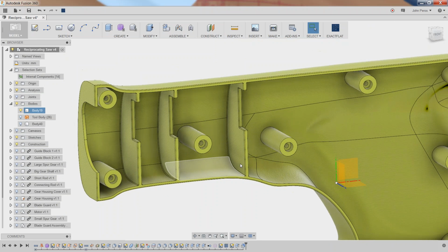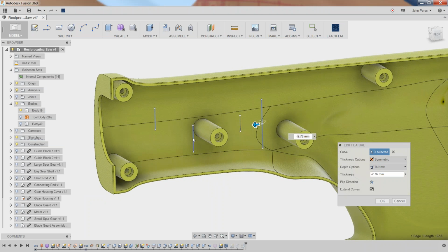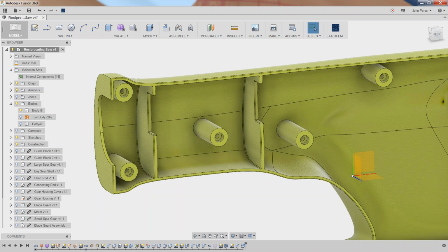those features. Now, this is a really robust way to do fillets, because if I do fillets by picking edges and then the edges change or move or get deleted, my fillet feature is going to fail in a traditional system. If I use this feature in Fusion where I'm inputting the features, if I go and say take out this middle rib, I'm not going to see any error in that filleting feature because the filleting feature didn't ask for edges, it just asked for the feature.